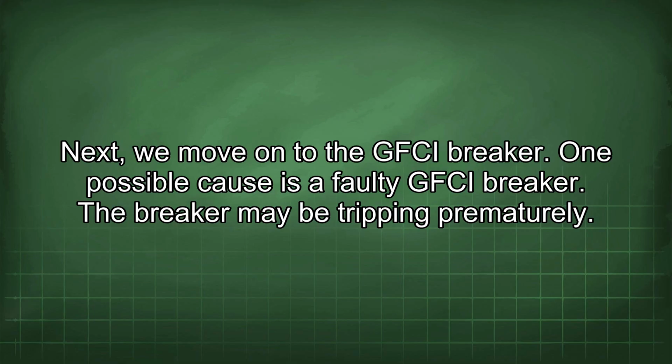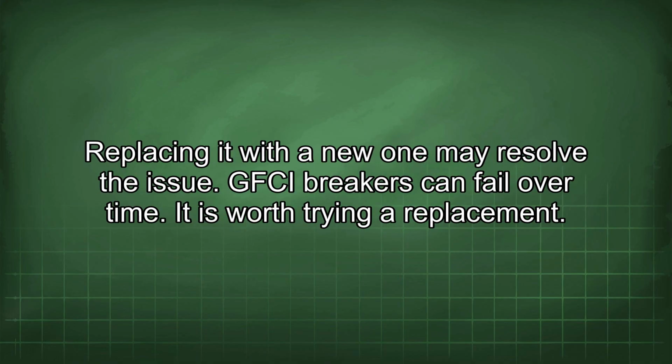Next, we move on to the GFCI breaker. One possible cause is a faulty GFCI breaker. The breaker may be tripping prematurely. Replacing it with a new one may resolve the issue. GFCI breakers can fail over time. It is worth trying a replacement.